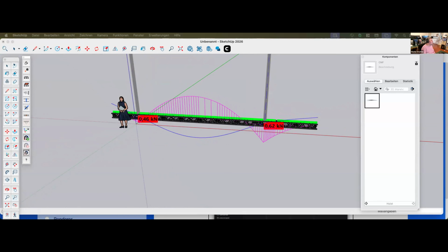The last thing in here for the simple thing, how it actually works, is that we use the point load tool. If I click on the point load tool, I now can select one of the trusses. I see a small highlight beam in here, and then I click again. Then it asks me which weight I want to assign in here.